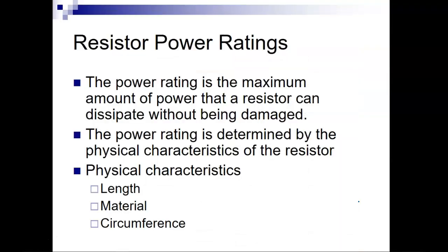All right. So the power rating is the maximum amount of power that a resistor can dissipate without damage. Just like a light bulb. What is a light bulb rated? If you put a 30-watt light bulb in a 40-watt socket, what's it going to do? It's going to be kind of dim, right? Will it still work? Yeah. Work very well? Not so much.